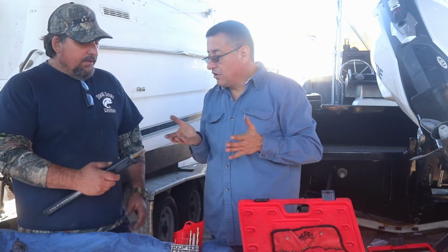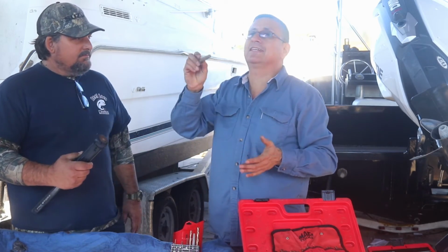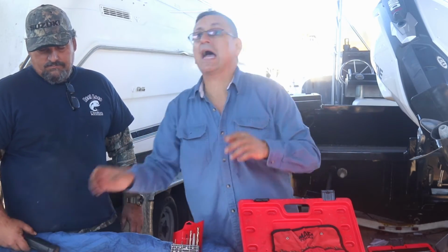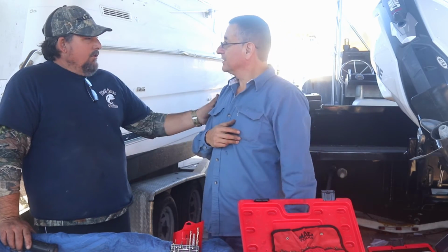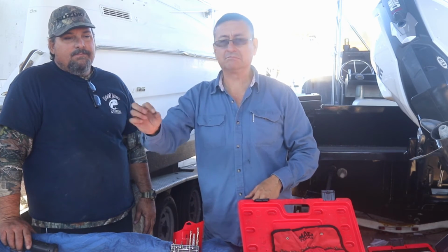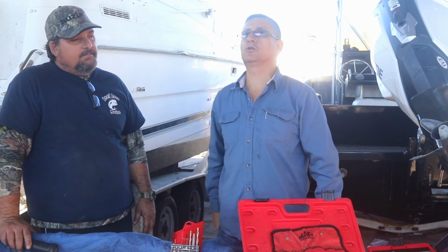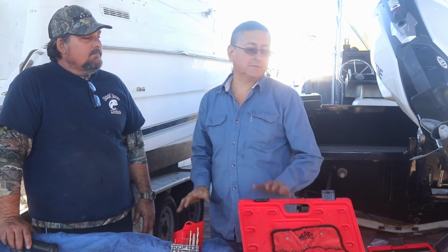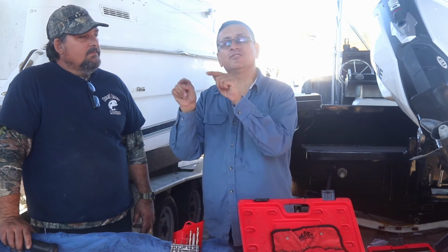Correct. And here's another bolt that's not good. This is not good. For that reason, a good inspector in this business needs a magnet in the pocket. I finished the installation of the air conditioner. Let me check. Those bolts are not good. Magnet. Replace that. It looks like a stainless steel, but it's not a stainless steel.